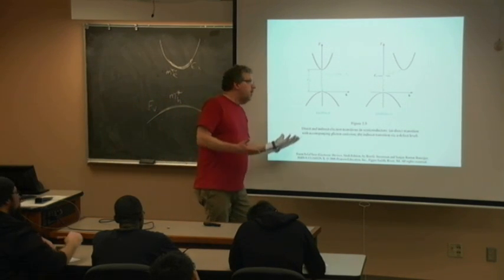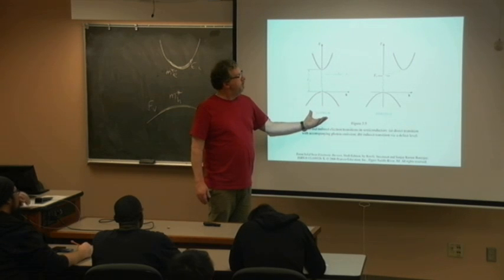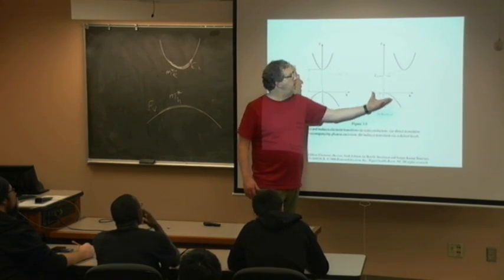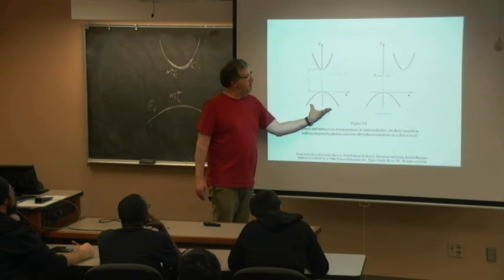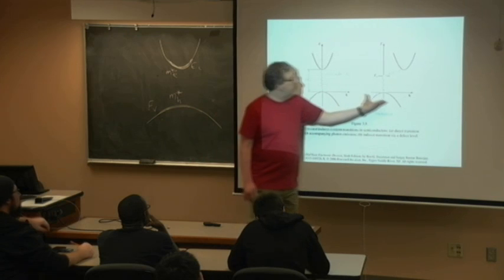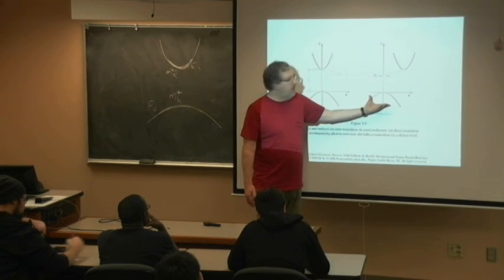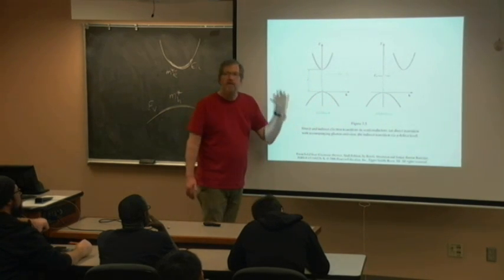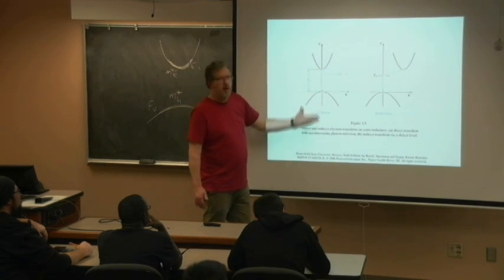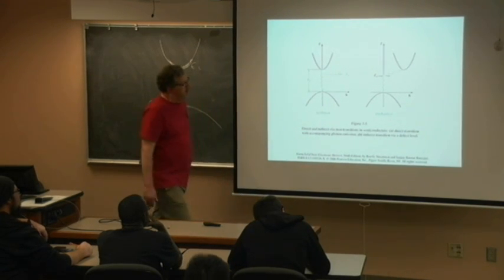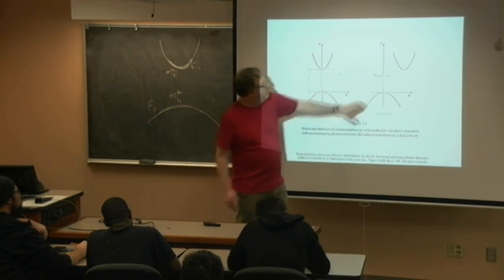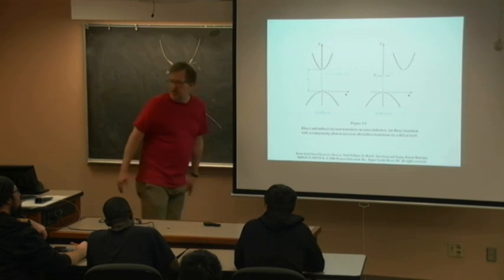So some semiconductors manifest as direct, and some indirect. Silicon and germanium tend to be here. Gallium arsenide, gallium nitride, and phosphide tend to be here. So silicon and germanium do make good electronic devices, but they make very poor photonic devices. So this is what is used for LEDs. Now silicon can absorb light, it just can't really emit light. So we have silicon solar cells.